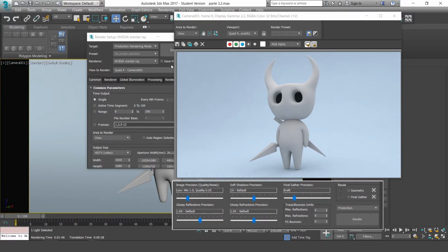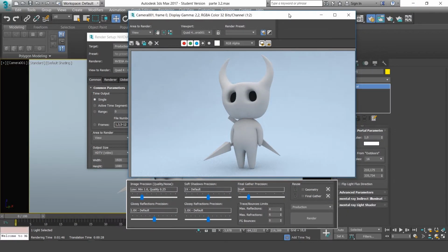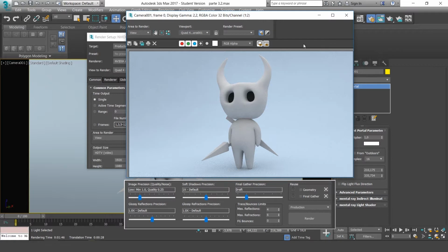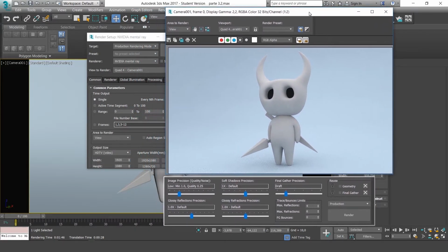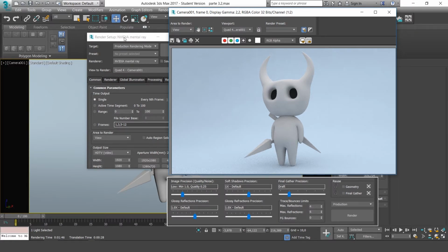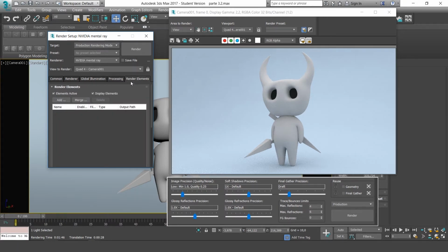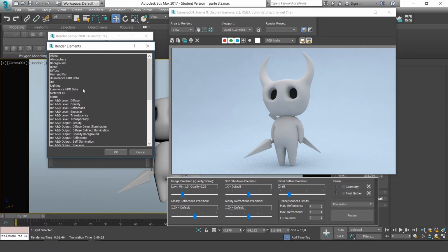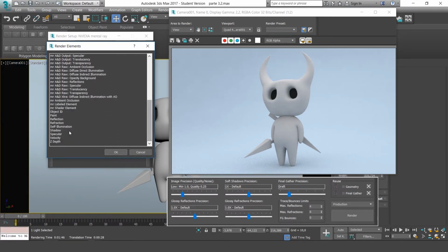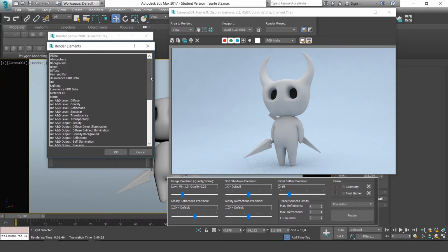We just used a portal and a skylight, the fill light, and this would just be a render of what's known as the diffuse map. We wouldn't use this for a final illustration, so to render our final image, there are a few more complex ways in this tab here. Here in Render Elements, we can add different texture maps to our model. We could use shadows, reflection, refraction, auto-illumination. This map is the diffuse map.